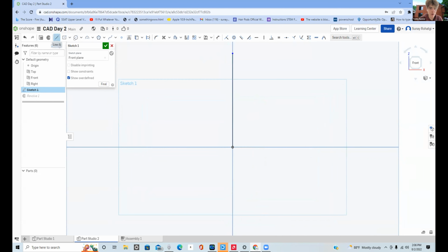So we have the axis in the middle, and then we want the line that comes out because the cap is angled. Let's start right at the beginning using the dimension tool so that the base is 10 away from here. I got it pretty close, but let's make sure it's 10 exactly. Then we want the top part to be another certain distance away, and let's make this 14. That's how you know that there's an angle. Then we want the height to be a certain way so that this line is fully defined, and I'll make it 20. Now you can see that line turns black because it's correctly defined.